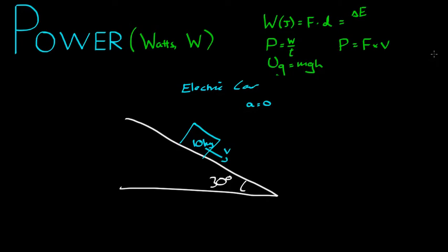So a few more knowns. Number one, the power of the engine is equal to 1,000 watts. And there is a frictional force acting up the plane of 250 newtons. The other force here is the driving force. Let's figure out the velocity this electric car has to be travelling at in order to maintain a constant velocity.